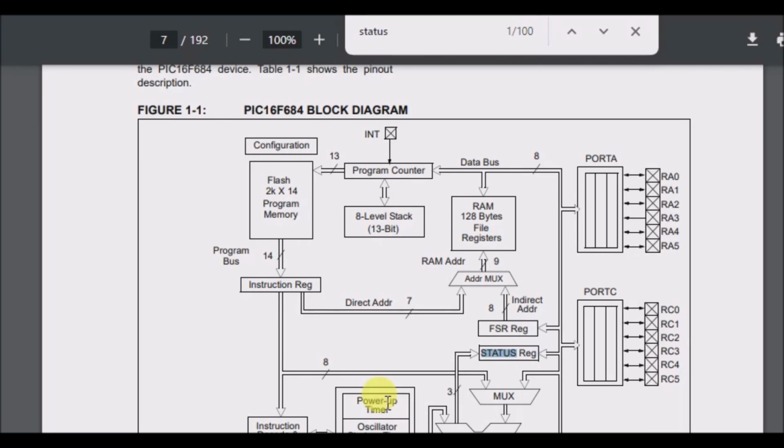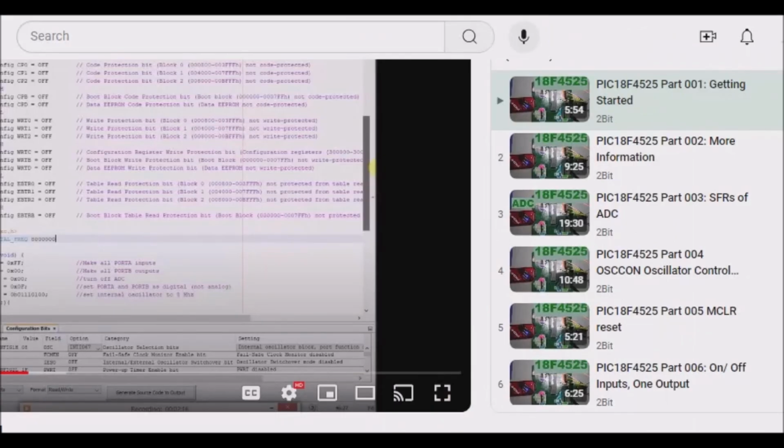So I believe in the PIC18F family, bank switching and writing applicable code for that is not necessary. And I forget exactly why that's the case, but I just happen to know that. On my channel, I have a fair number of PIC18F videos, and bank switching was not required in programming the 18F chip, but it is necessary in the 16F family of chips.